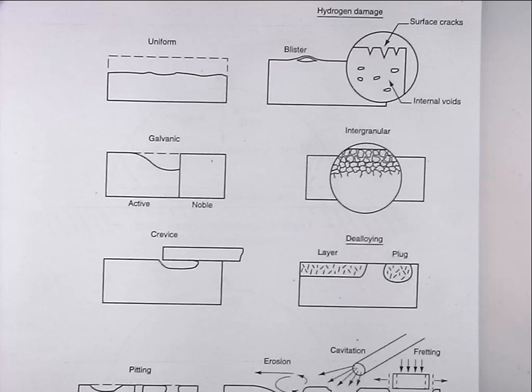If you remember, we were talking about types of corrosion. We just started and we had identified uniform corrosion, which is the easiest form to detect because you're getting a steady reduction in thickness or cross-section of your material, and it's very easy to observe. Once you go into localized corrosion, things get a bit more difficult because your structure can be apparently in fairly good condition, but somewhere along that structure there is some localized attack which could cause failure.